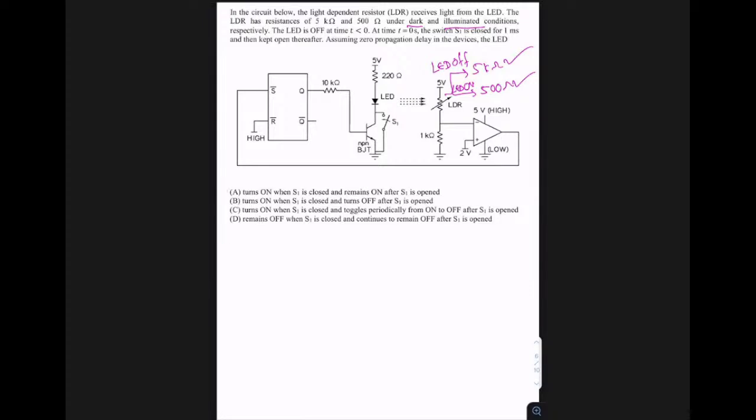And if you see, it's actually an SR flip-flop, but the inputs are S bar and R bar, right? So if you want to make use of the truth table of the SR flip-flop, you have to think with respect to S and R, not with respect to S bar and R bar. So see what's going to happen. Any idea, please? It's a good thinking-based question.